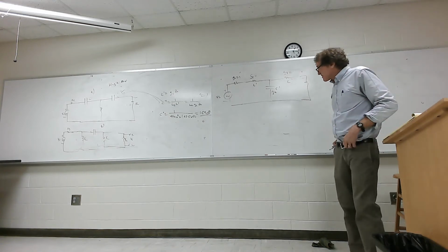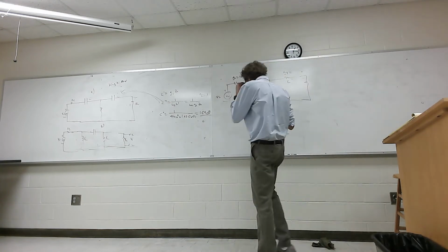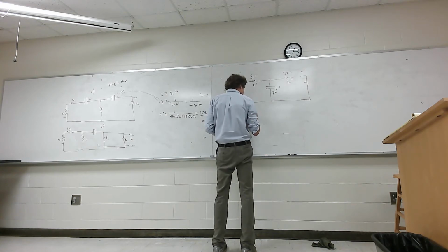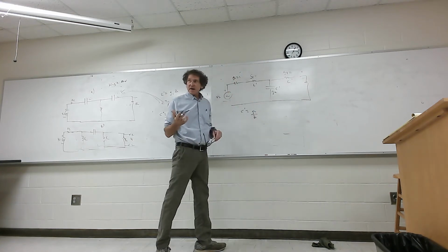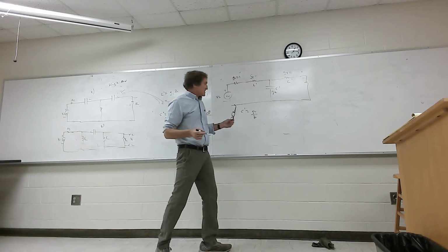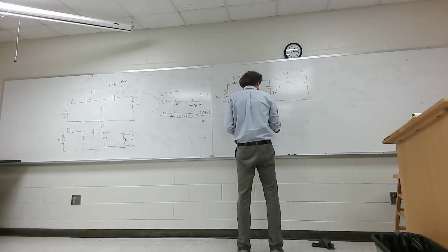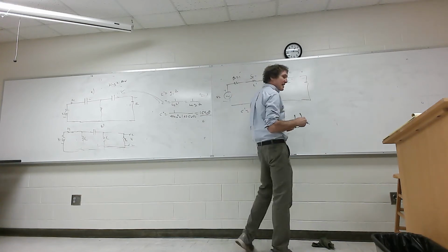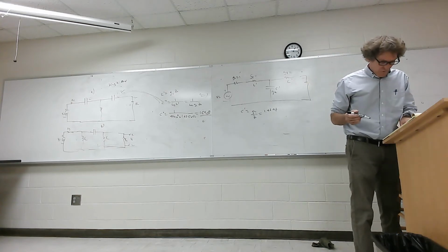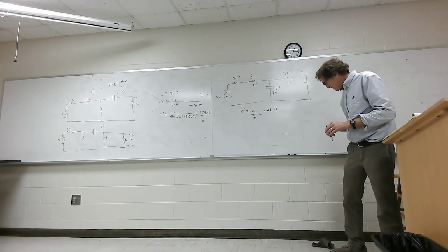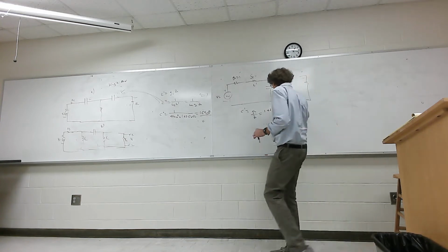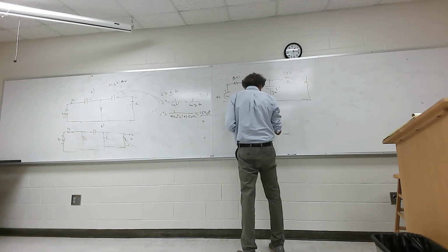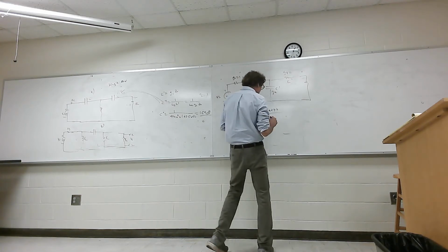So now the next thing we have to get is this C prime here. Now remember, C prime for this one was simply going to be the value of G2 divided by Z naught. So we need that value first. Y'all follow me again? What I'm doing? G2 was what? 1.1747, I think? I have it written down here somewhere. 1.147, sorry. 1.14747 divided by 50, so that's going to be C prime.